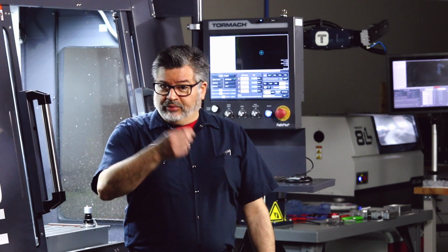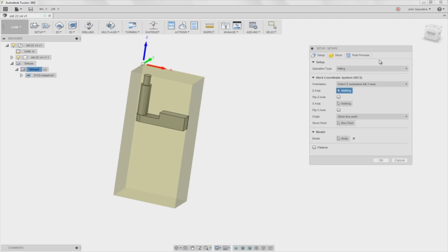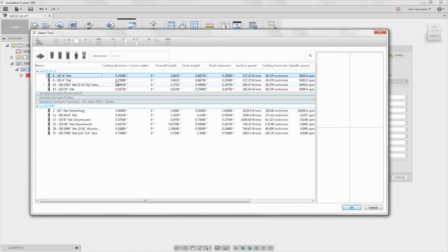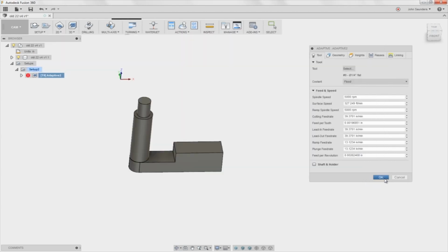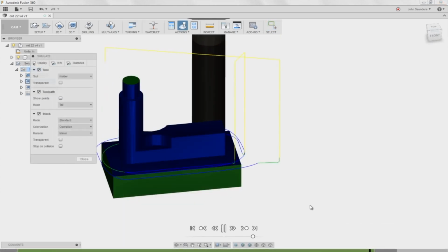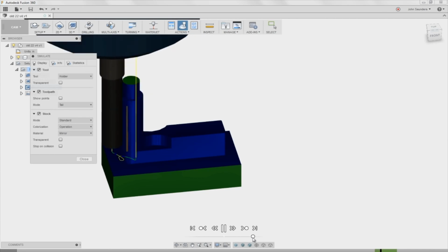You take what you designed in CAD, you bring it into CAM, and you set it into this virtual environment, in a virtual mill, into virtual work holding, and you choose the virtual tools that you will eventually use to make your real part. All of these virtual components accurately represent the real tools and techniques you will eventually use to manufacture your real part.